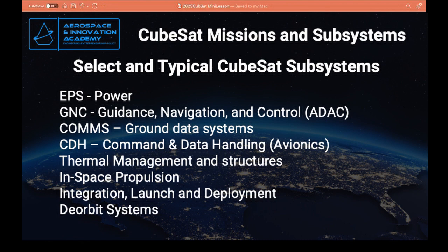So typically large spacecraft will use a Ku or a K or a Ka band. Those represent different frequencies. The CubeSats that I've used, we tend to be in the 1.6 gigahertz range on the frequency, and that's in the L band. The CubeSat we talked about last episode, Marco, that went to Mars, it actually used the X band. It needed a different band.